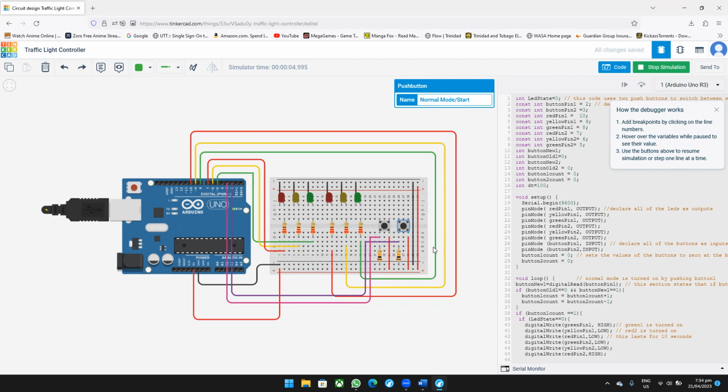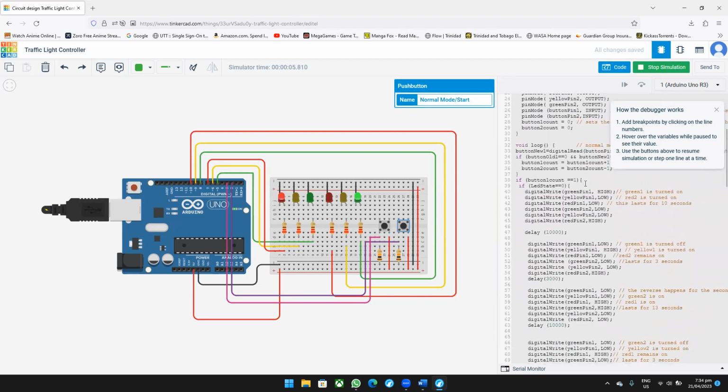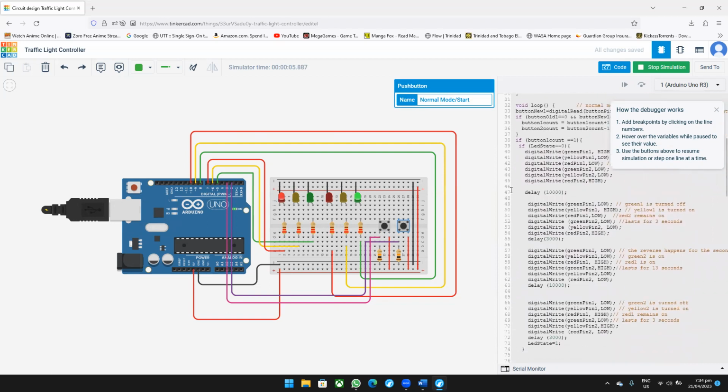In normal operation mode, the traffic light will cycle through red, yellow, and green LEDs in sequence. Ravi, this is a list of the codes. The green will be around 13 seconds, 10 to 13 seconds. We'll go on yellow for about 3 seconds, and this will go on red for about 10 or 13 seconds also. It will be in the code here, 13 seconds for the green.